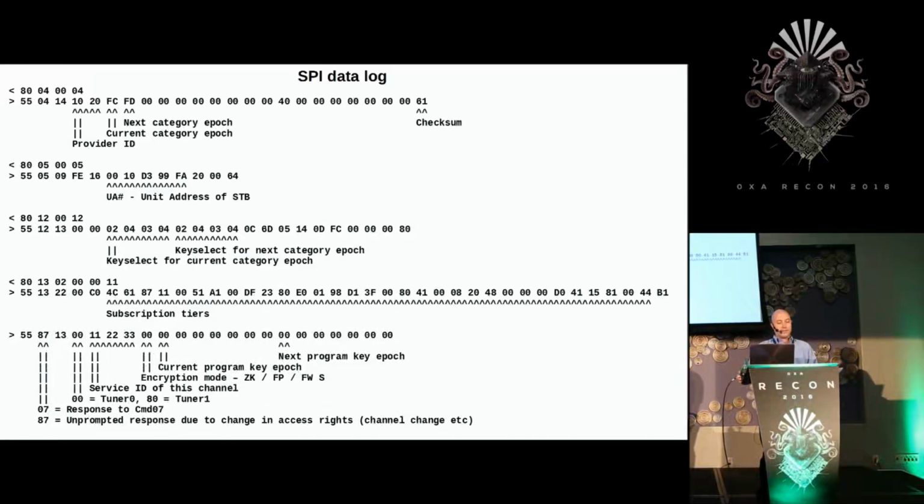There's also the set-top box main controller, which tells the ACP which PIDs it should decrypt, and which PID has the ECMs, and that's done by the SPI interface. The ACP never sends any keys on the SPI bus, and it only receives the category keys in encrypted EMMs on this bus.